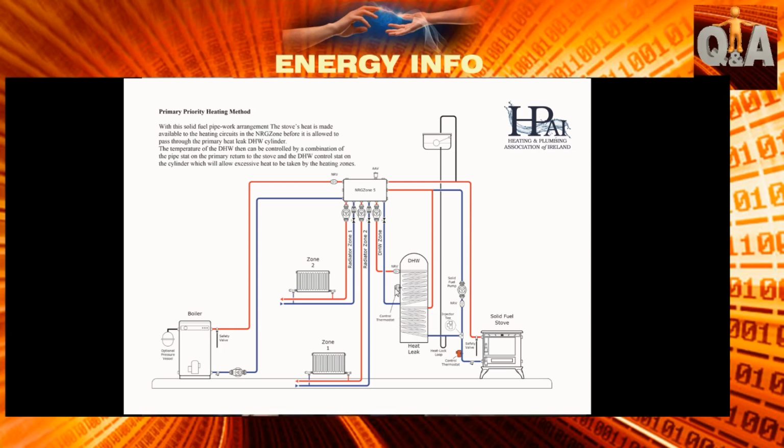So basically that cylinder stat is only controlling your pump. It would be used to make sure that the water has a chance to get warm, but at the same time you can steal the heat. You can heat the cylinder with the return water, which you should still keep above 55 degrees, but it means that you can control the temperature of the cylinder, which really is unheard of without that type of system.